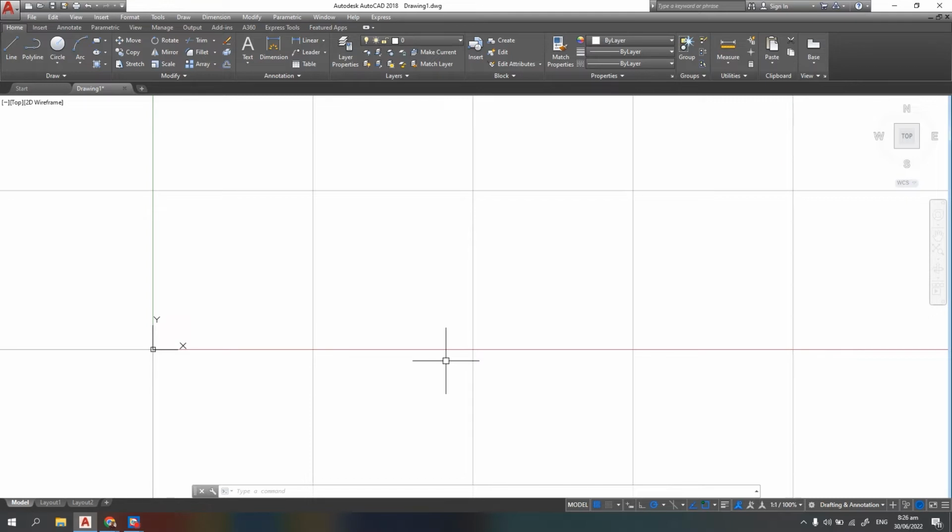Then what you do next, so you can draw effectively on your coordinate entry, is to turn off this one. This is the object snap. Turn it off. You can see that it is off if its color is not blue, or it has no illumination. This one also, you can turn off object snap tracking and the polar input.